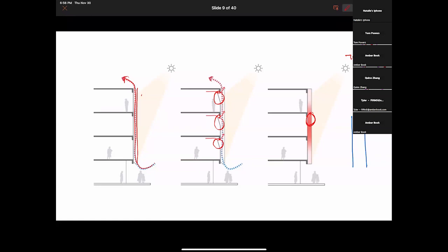If you've ever seen toilet paper over a radiator in an old building, you can see it waving back and forth as the heat rises from the radiator. It's the same principle, it's just convection. So a convective loop, from a thermal point of view, is a bad thing. It goes up one side of a cavity, typically a wall cavity, and back down the other.